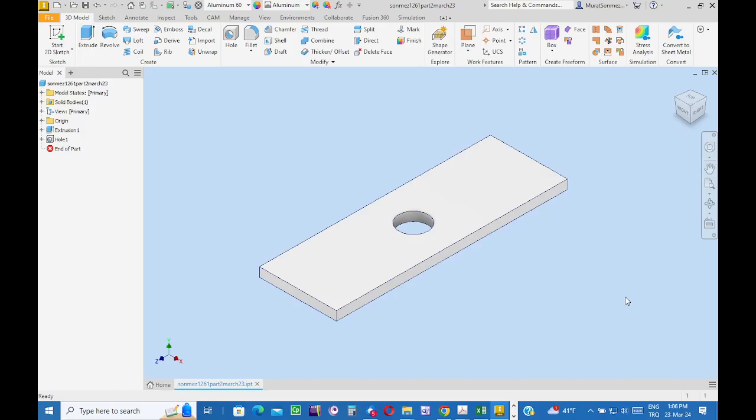If you forget applying the pack and go process, then the other person can open the solid model file, but cannot find the models of some components and also the geometrical constraints for the components. In short, there will be a serious difficulty at the side of the other person. Inventor will ask lots of questions: where is this file, where is this file? How many files? On the order of a few hundred files.